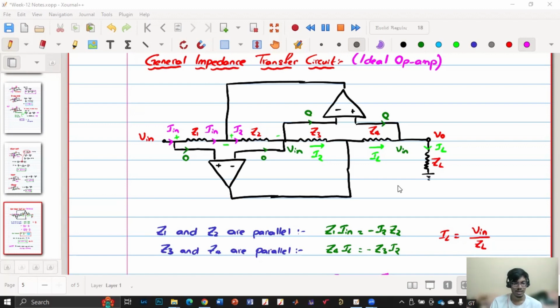Whereas the inductor's size is a constraint. If you see any inductors of very low current rating, inductor sizes are also very small. But in any application, inductor size is a constraint, not the capacitor size, because inductor size will drastically increase with the power rating.